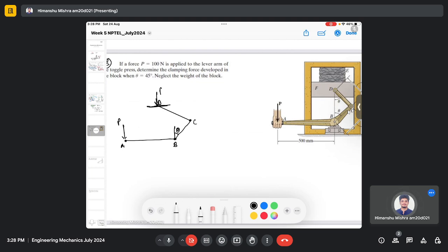Let's say it's force Fe, and let's say this is my block, and there is a normal force acting because it is in contact with this part, so there will be a normal force as well. Now we need to assume the virtual displacement. There is a force acting at point A. So let's say my virtual displacement looks like this.